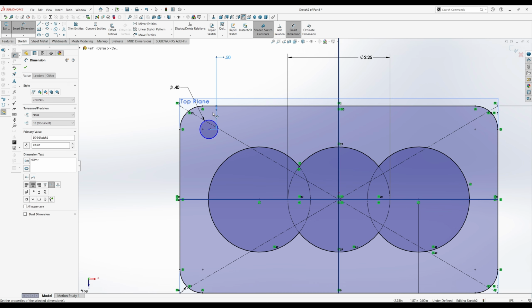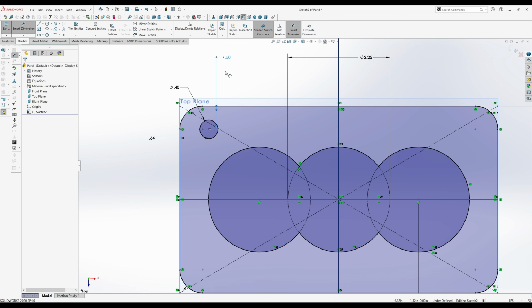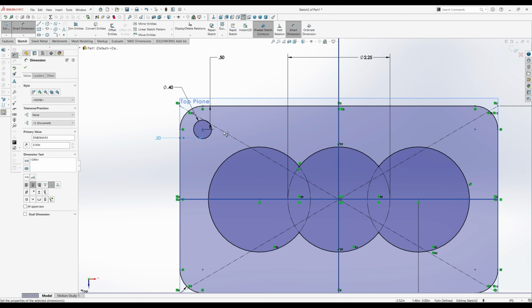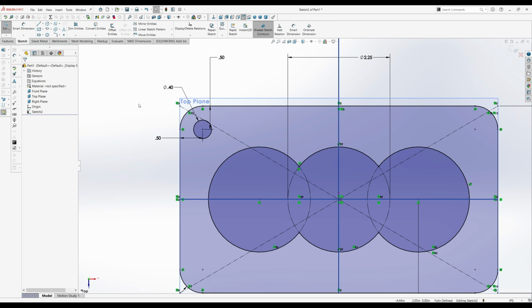And if you look at the dimensions that are given, you have 4 inches wide of the gasket and 3 inches is center to center of the holes. So you subtract the 2, divide by 2, and you'll get 1/2. So you know it's 1/2 in the other direction as well. So that's how I came up with this first dimension here. And so we have the 2 dimensions and it's set.